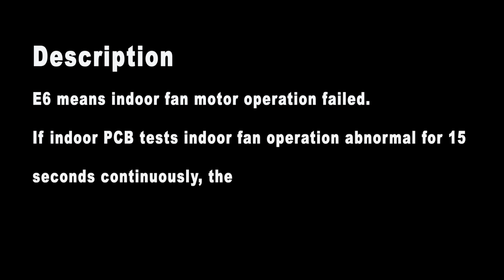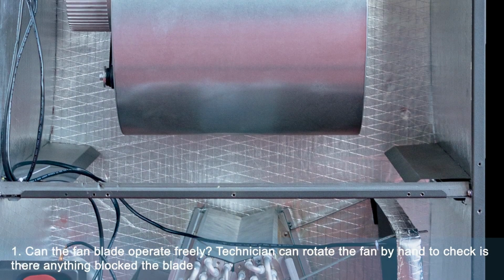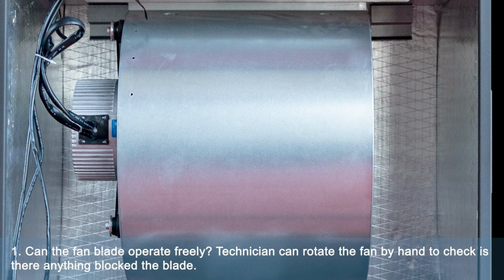E6 means indoor fan motor operation failed. If the indoor PCB tests indoor fan operation abnormal for 15 seconds continuously, the wired controller will show the E6 failure code. 1. Can the fan blade operate freely? The technician can rotate the fan by hand to check if anything is blocking the blade.